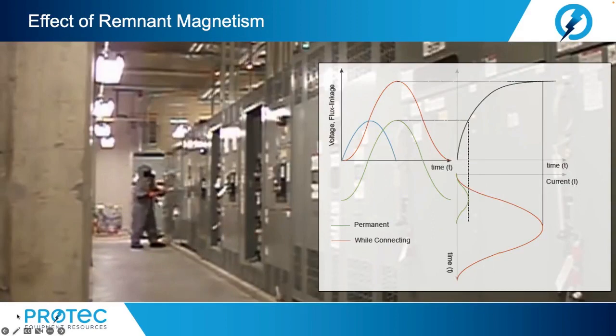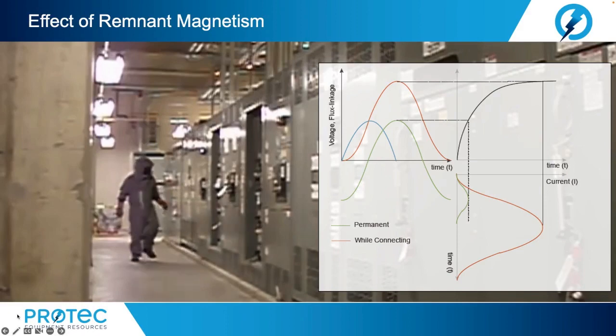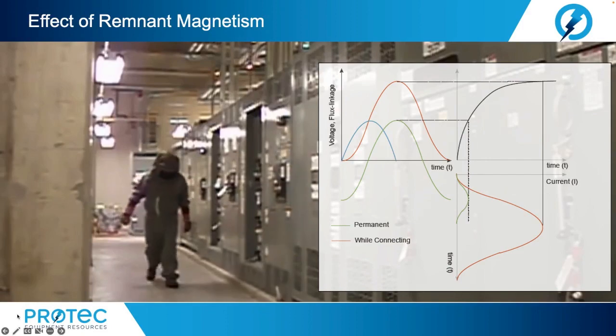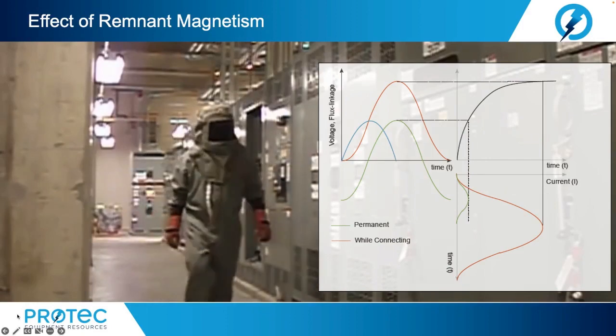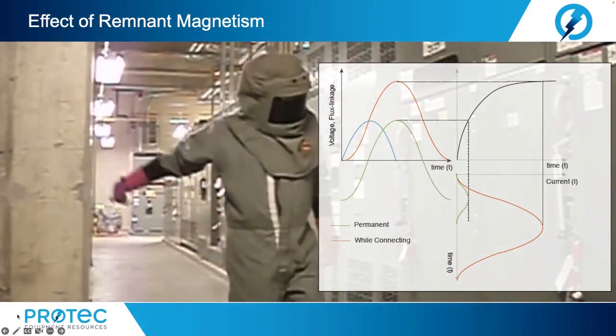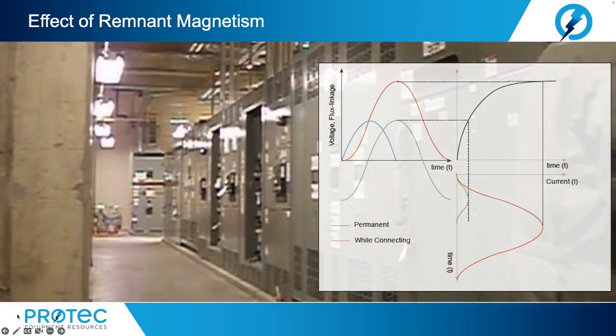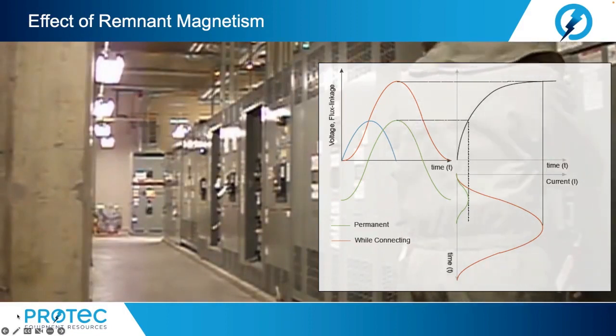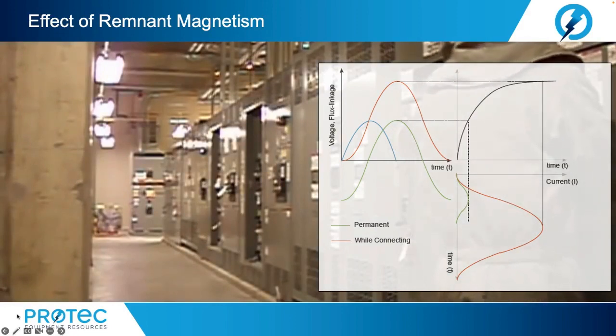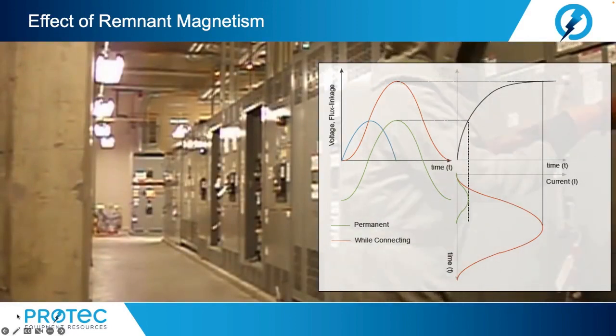Now, when an electric power transformer is switched on from its primary side with keeping its secondary circuit open, it acts as a simple inductance. When an electric power transformer runs normally, the flux produced in the core is in quadrature with the applied voltage as shown in the figure. That means the flux wave will reach its maximum value 1/4 cycle after the voltage wave reaches maximum value. Hence, as per the wave shown in the figure, at the instant when the voltage is 0, the corresponding steady-state value of flux should be at negative maximum.